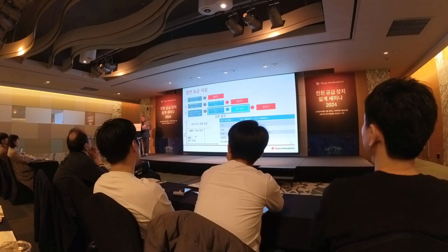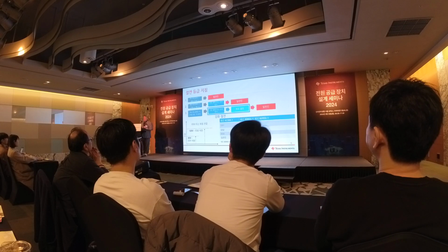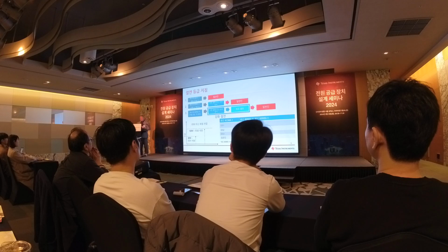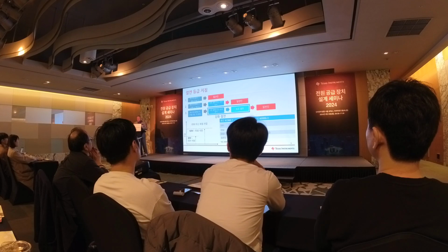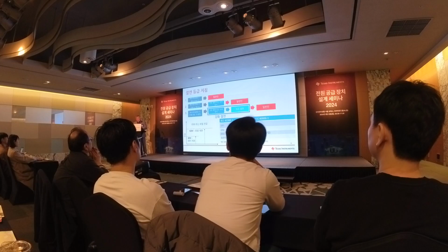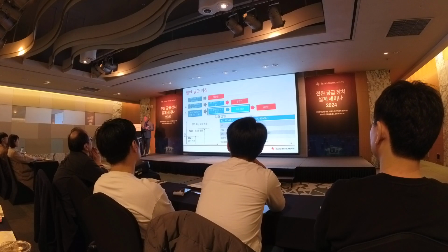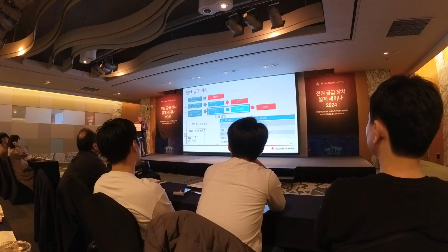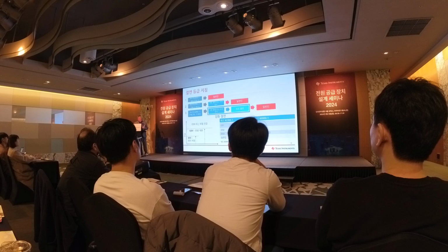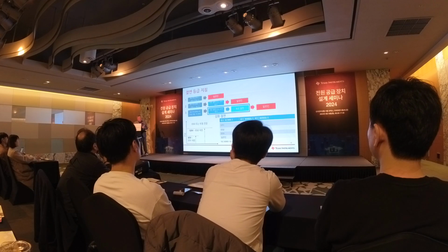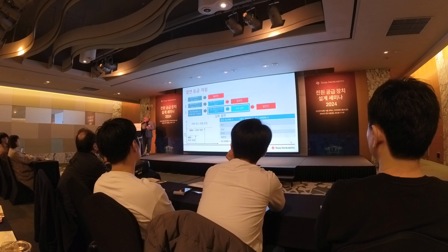So let's take a look at some of the guidelines for insulation and how they are used to protect an ordinary person or user against electrical shock. The first thing that we need to define and look at are the energy source classes. So we have energy source class 1, 2, and 3. These are defined by different IEC standards as well. And what we've shown here are energy source class 1, 2, and 3, and then from the different standards, what those particular voltages are.